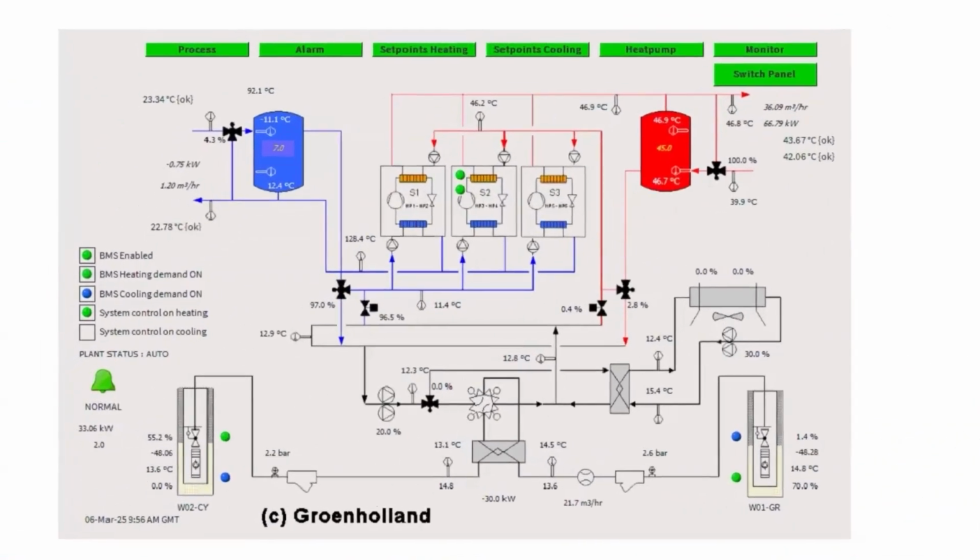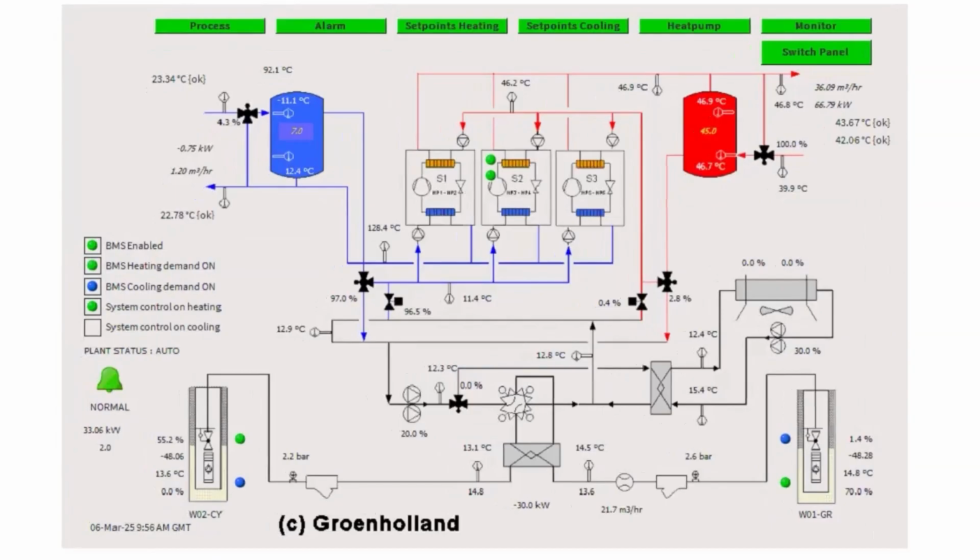And as there is water now on the heat pump side, we do not need a plate heat exchanger between the building on the cold or the hot side anymore. We have a direct connection on the building side, but the plate heat exchanger between the groundwater wells and the system.